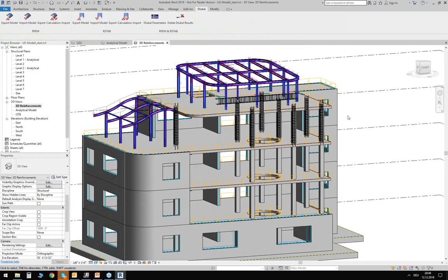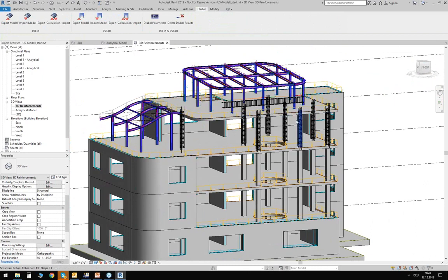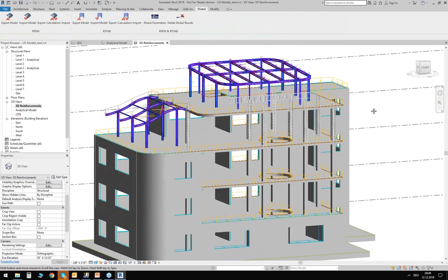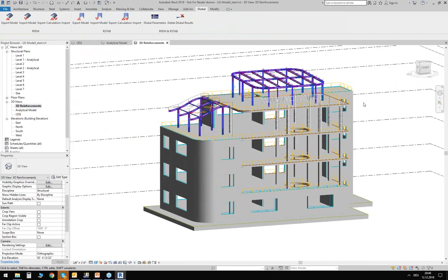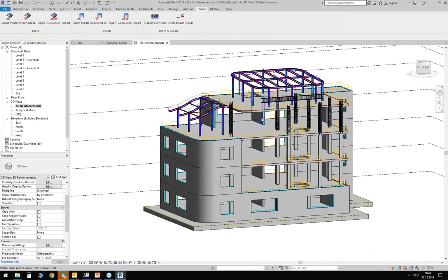This would be the first scenario that I wanted to show you. So the exchange between RFEM and Revit and using the global model, so the complete analytical model. And you could theoretically continue here. You could change or update or add additional things in Revit. You can update the RFEM model. You can design again the RFEM model and export these newly found results or anything else back to Revit. So back and forth, and this is what Amy said, it's a bidirectional interface.